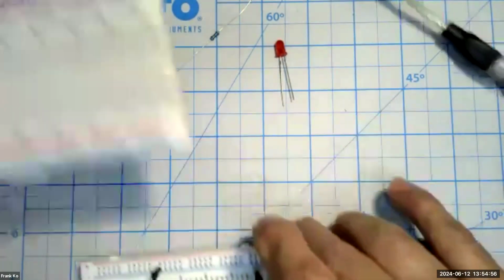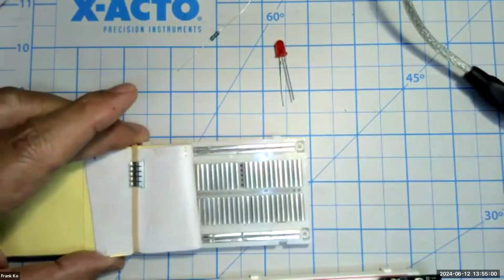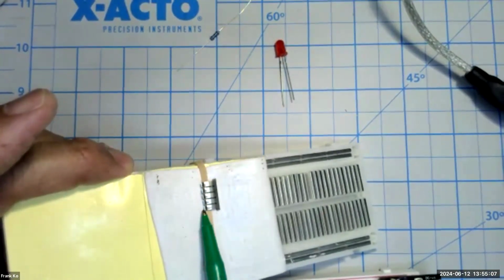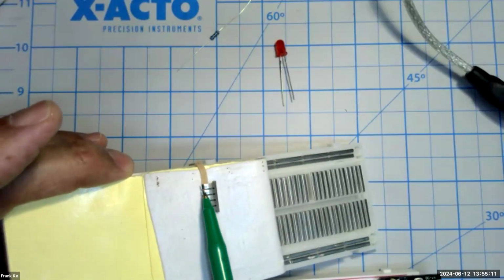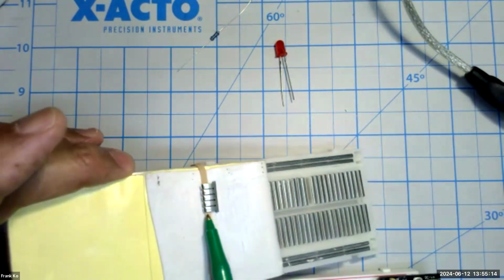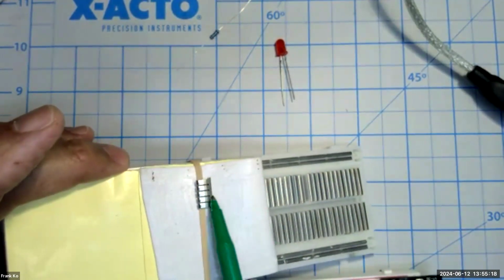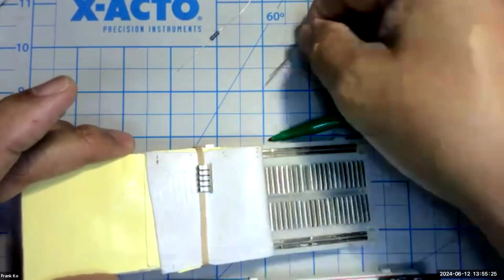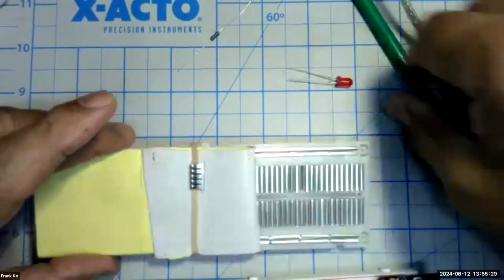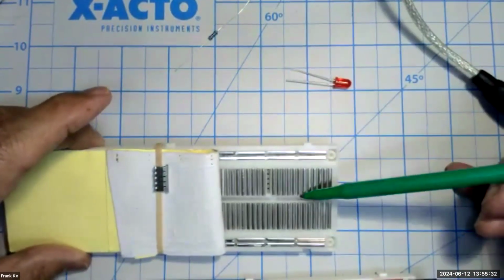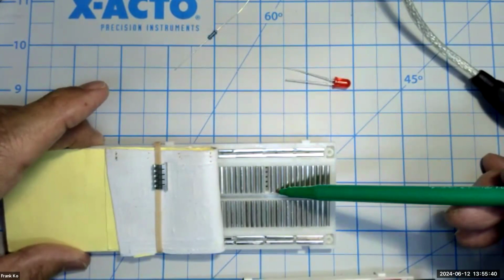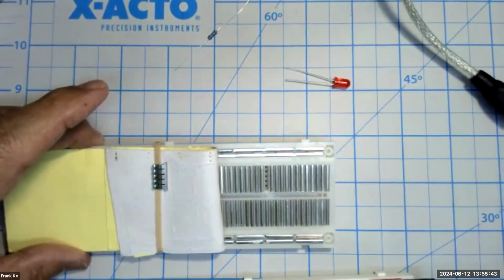Why? Because of a number of reasons. Many reasons could be that these spring clips that I showed you in the previous topic 1 video may have some residue in them from the manufacturing facility, maybe a slight film of something that prevents good electrical contact from the wires of your LED or other devices that are shoved into the connecting points, and therefore things may not work out as you hope. Yes, the continuity pattern is supposed to be like this, and we're supposed to be able to rely on power rails working consistently, and we're hoping that the tie points part of our breadboard works consistently. If, however, that doesn't happen, there are a number of reasons.